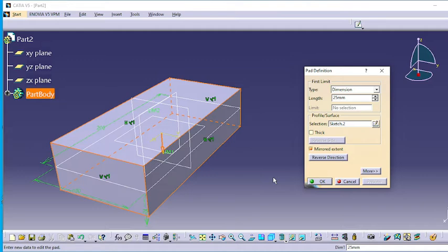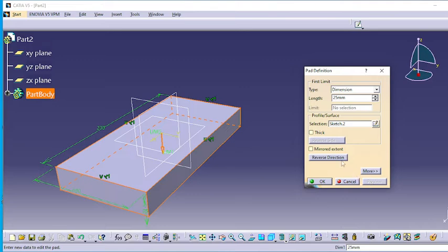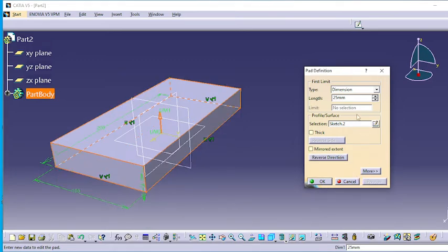For example, if you require height on one side only, then you do not use the mirror extent option. Yes or no? You switch this off. In whichever side you want the height, you use the reverse direction, and enter how much height you want.